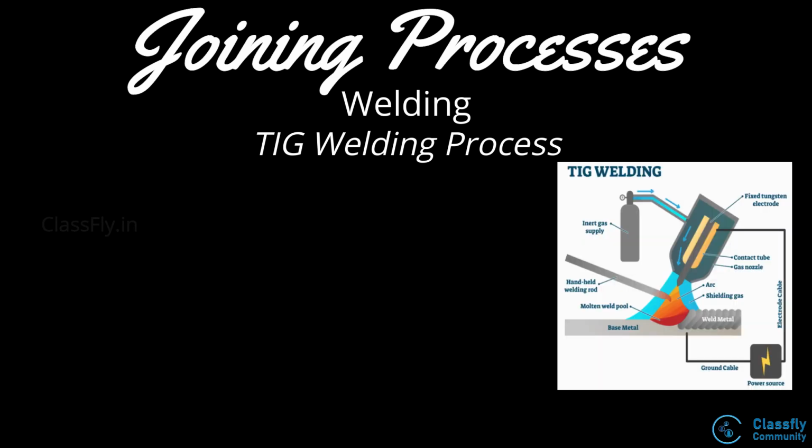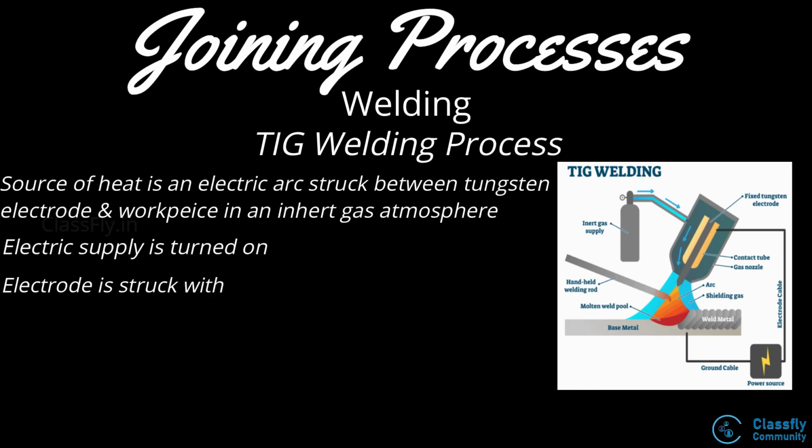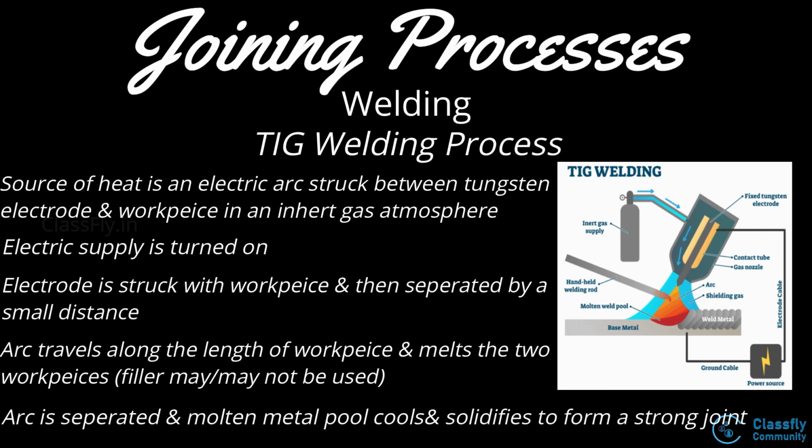Similarly, we saw the working of TIG welding, that is nothing but tungsten inert gas welding. This is also a welding process in which the workpieces are joined by the heat obtained from the electric arc struck between the non-consumable electrode, which is made of tungsten, and the workpiece in an inert gas atmosphere. Then we moved on to the concept of belt drives.